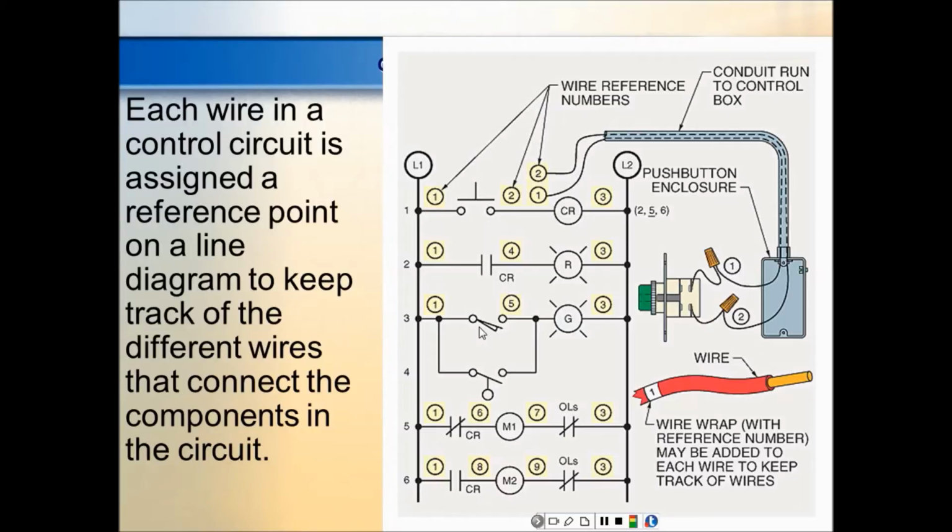In fact, when we wire these things up, we don't go back to the power source. We jump from device to device. You can't go back to the power source because if everyone went back to the power source, I would try to hook 6 conductors under the same terminal block. Now legally, the maximum is 2. As soon as you put that 3, you're going to have problems. Over time, it's going to probably come loose.